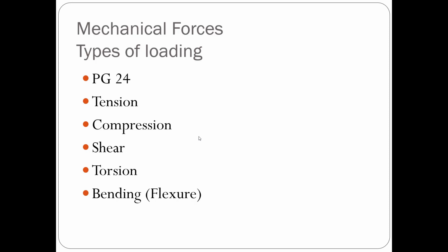And in a lot of cases, we want to avoid putting our through thickness in tensile loading. Actually, in the welding code books, it's against the code to put plate, like steel plate, in through thickness tensile for a structural application. That's how bad it is compared to the other directions. So tab that page, be able to answer some questions about rolling direction.